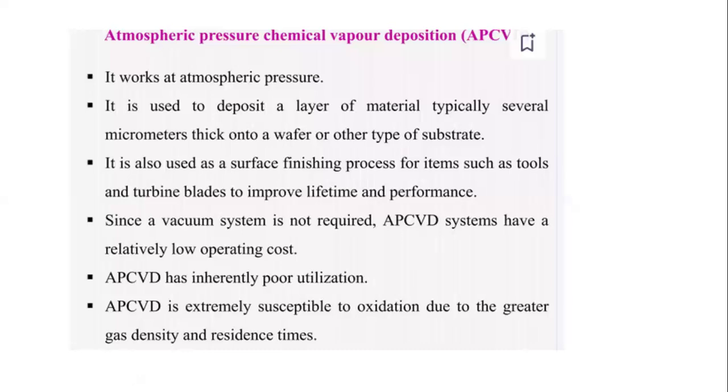atmospheric pressure CVD systems have a relatively low operating cost. Atmospheric pressure CVD has inherently poor utilization. Atmospheric CVD is extremely susceptible to oxidation due to the greater gas density and residence times.